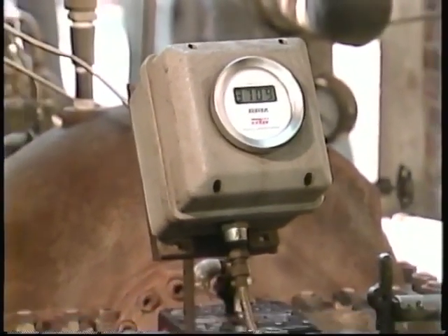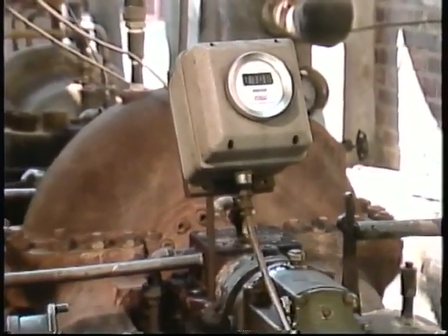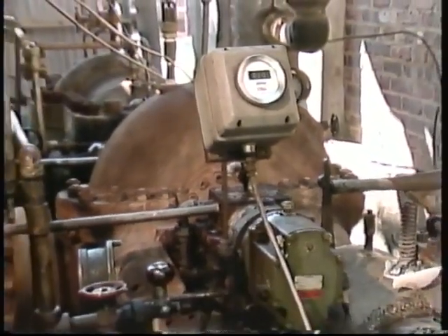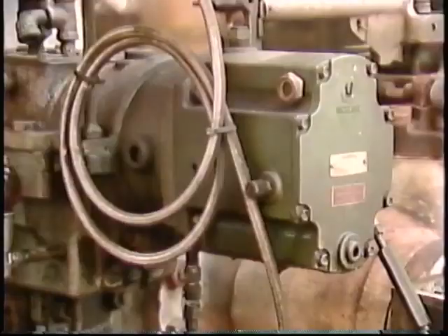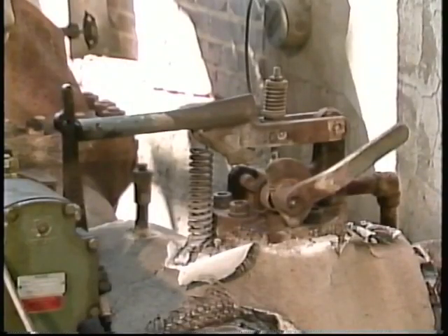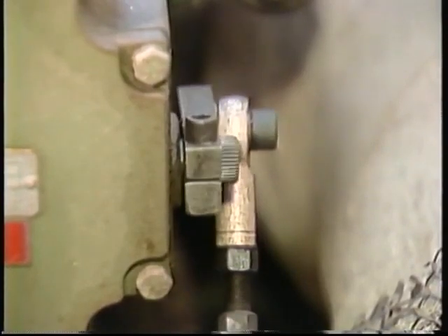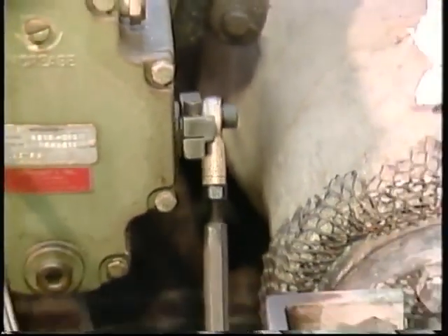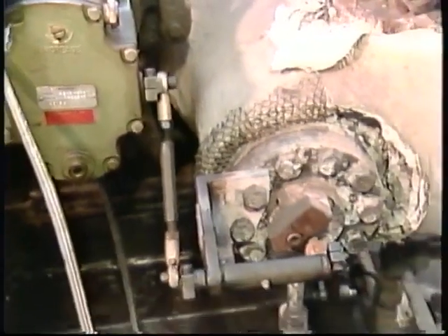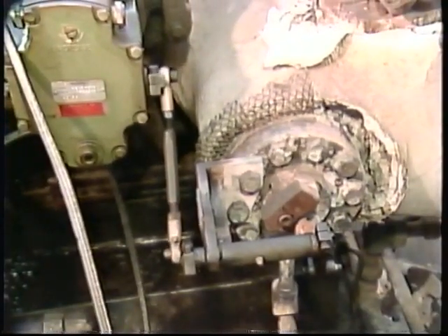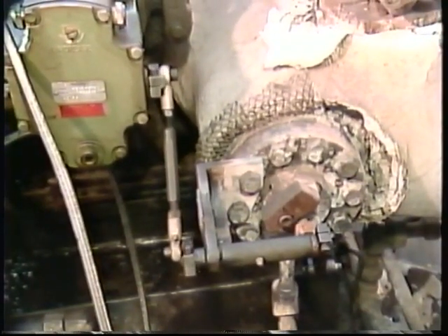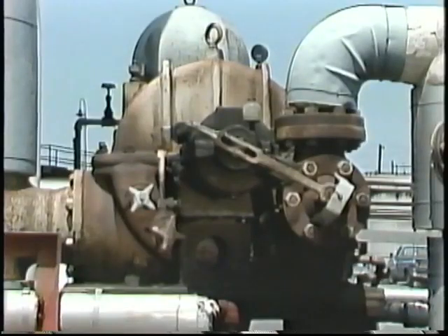Other operating problems are related to speed and involve the operation of the turbine's speed control system, including the governor and the overspeed trip. If the governor is hunting, examine the linkage to make sure it operates smoothly and isn't binding. Also, check to make sure there's a sufficient amount of lubricant for the linkage. Sometimes, an otherwise normally running turbine may hunt when its load is higher or lower than normal.